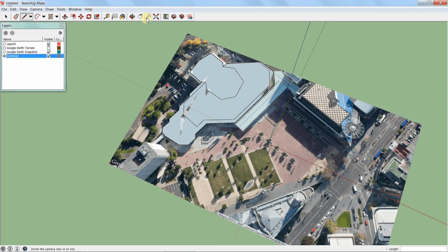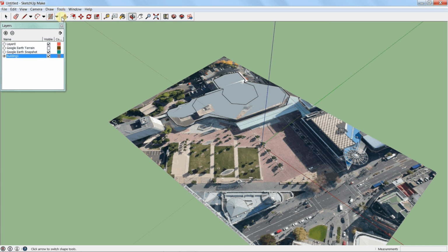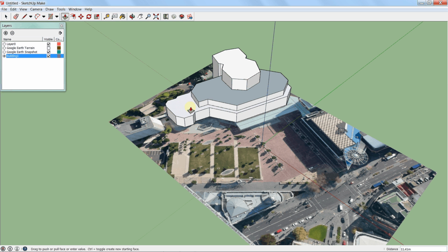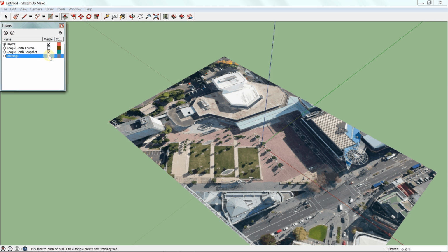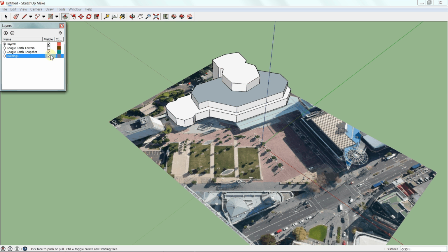And what we can do now is we can extrude those levels. So let's just change our position. Let's come around there. And we have what is called the push-pull tool. I can click on that, pull that out. Click on this bit, pull that bit out. Click on that bit, pull that bit out. And just play around with it. You can see that it works on all surfaces. I can do it that way as well if I want, but we don't want to. So there's just the start, quite simply the start of how one can start to layer up a building using those simple tools. And also, if I go back to layer 0, I can turn that layer of the building on and off.